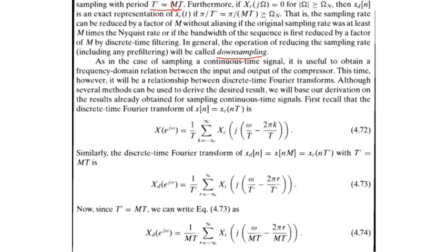And most of the time, in many applications, we use downsampling as a pre-filtering. So you know the Fourier transform of x[n]: whenever I have a continuous-time signal, I will sample it like x_c(nT), and the Fourier transform of x[n] will be X(e^{jω}), and after sampling we get 1/T times these copies of the original signal.